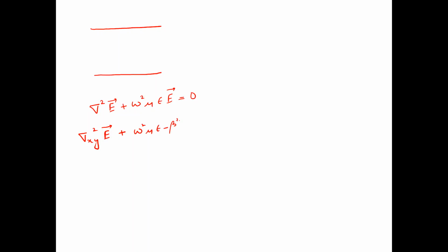So far what we have seen is that if I have two or more conductors, with confinement in one direction or any other direction, then because of Maxwell's equations, the wave equation, which in the transverse direction is the Laplacian of E plus (omega square mu epsilon minus beta square) E equal to 0, we end up getting solutions which are discretized.